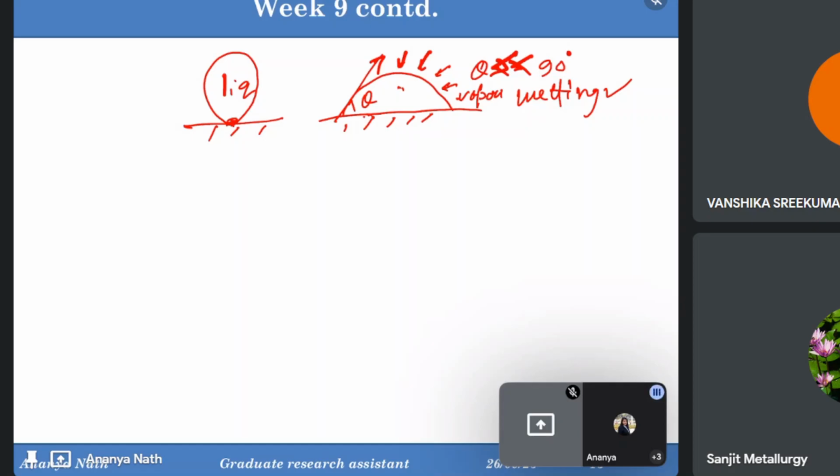Magnesium addition disturbs the oxide film on aluminum and lowers the contact angle, as it has good wettability with the SiO2 which is present on the SiC surface. So these are again some typical examples specific to one application, one metal matrix composite. Ti addition leads to absorption of the Ti and formation of TiC, which has better wettability.